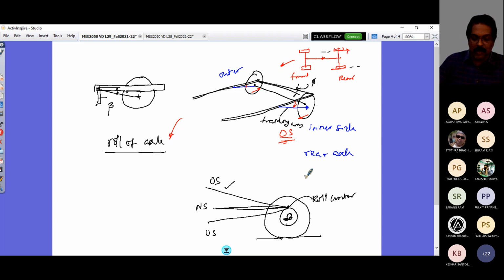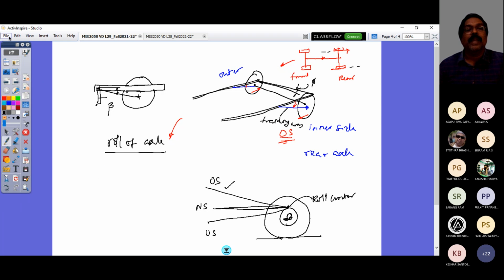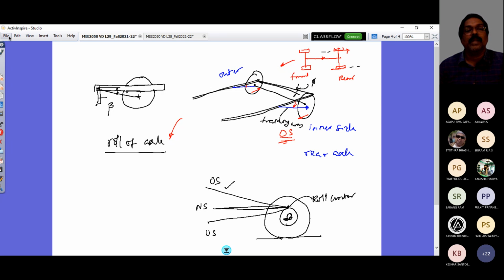So this is the reference to inclination of the suspension roll axis in a solid axle suspension. We looked only at the rear wheel, and we were able to discuss this roll steer effect. I stop this lecture at this point, and in the next class we will look at 3 more points additionally, which completes the additional effects on understeer gradient due to design aspects as well as operating conditions, all accounted for, right?